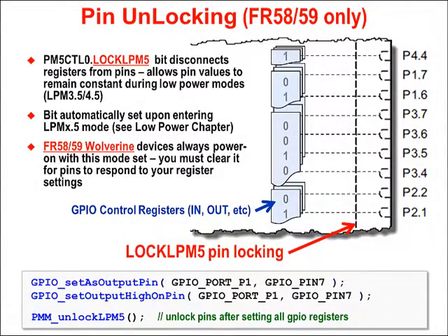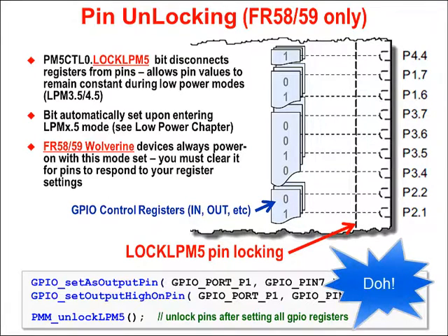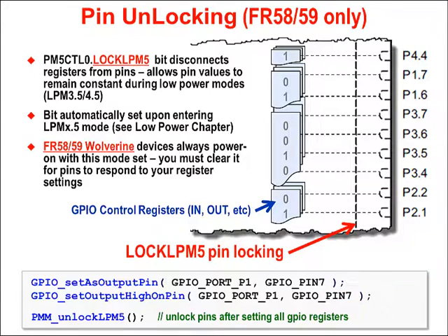You'll probably get burned with this at some point along the line. I don't know why the LED's just not flashing. I don't know what's going on. I know I set the registers right. I can just say that from personal experience. Then you go, oh, that's right. Forgot all about that. Got to unlock the pins. So it's just one of those things that you have to remember to do on these new devices. It is a nice feature. It's just you have to be careful that you make sure you do this.